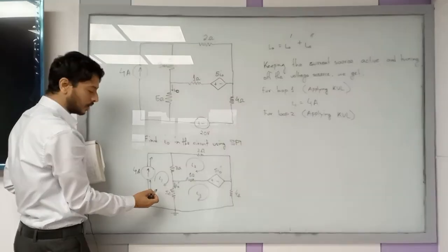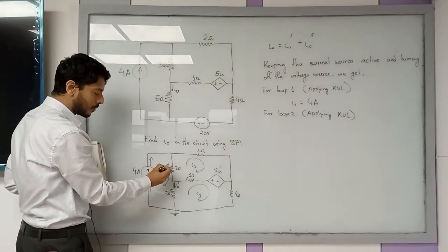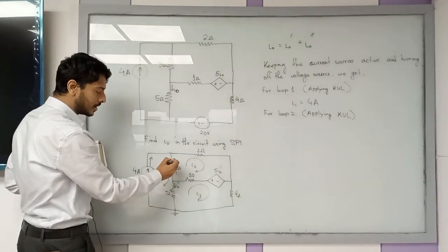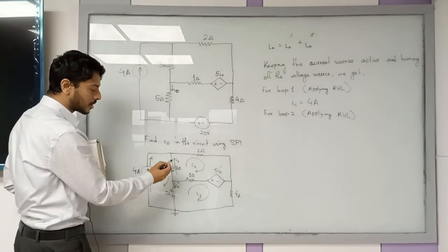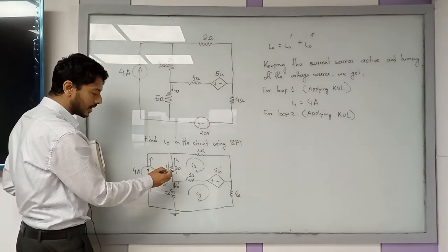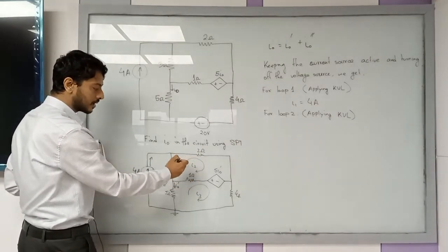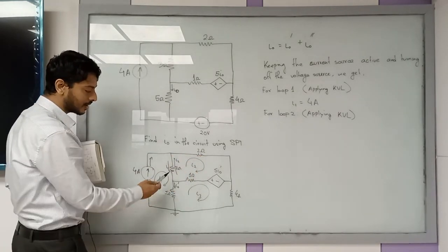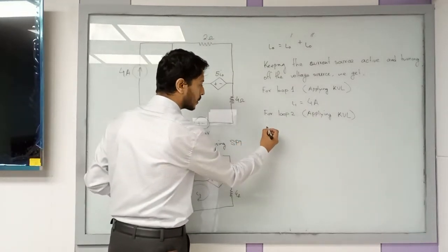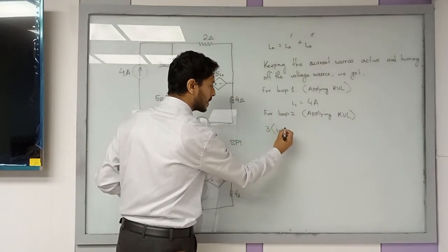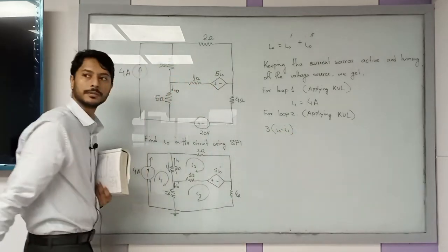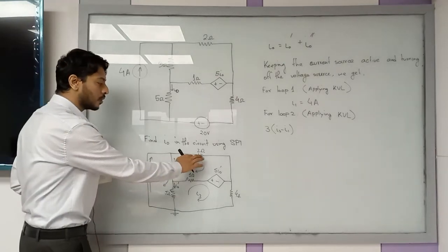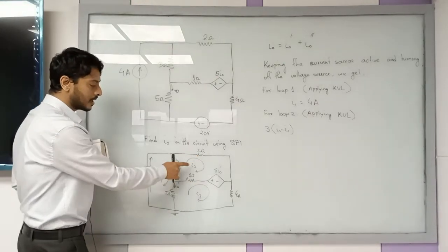And this is your secondary loop. At the secondary loop, I1 current is passing in this direction, 3 I2. And in the primary loop, I2 current is passing in this direction, I2 minus I1. So I2 minus I1 should be the resulting flow of current in this direction, right? So that current should be multiplied by this 3 ohm resistance. So I2 minus I1 times 3 ohm should be the voltage drop. Okay? Then you have 2 ohm, which should be multiplied by only I2.